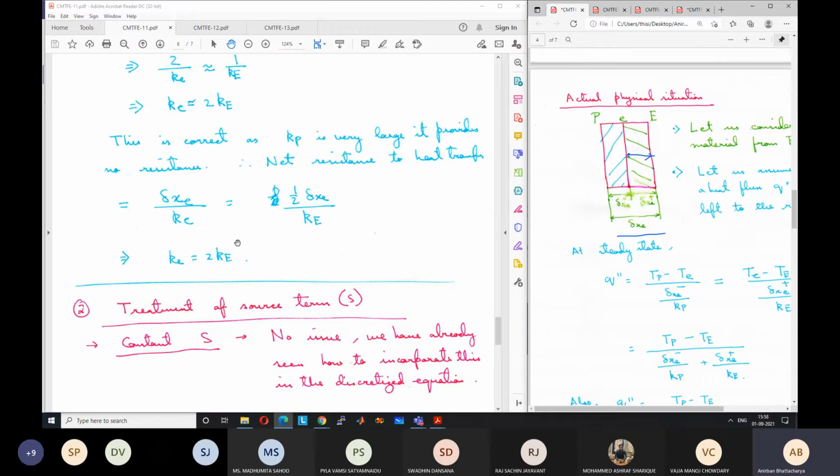So there is a junction between the metal fin and the PCM, phase change material. If this is the case, and if we do not take the harmonic mean and take just the linear mean, there is a chance of error, or we have to take very fine grids. If we take the harmonic mean, it will give us a much more accurate calculation at the interface between the metal and the phase change material.